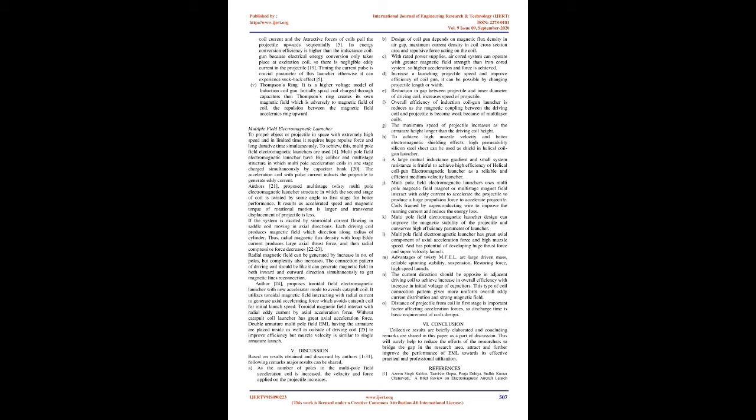That shows electric energy produced by the capacitor bank is transferred into the catapult coil, which energizes the acceleration coils to create a magnetic field. The projectile inside the acceleration coil experiences a mechanical force given by equation 14. The force generated on the projectile depends on mutual inductance and the magnetic diffusion process in the coil.